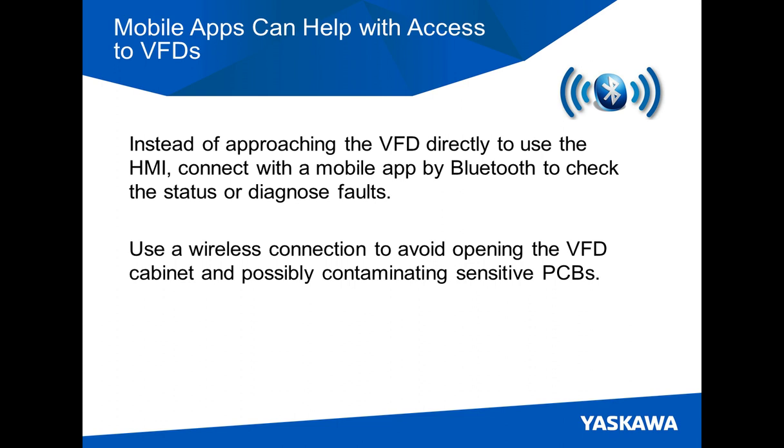So let's talk about how mobile apps can help with access. Instead of approaching a VFD directly to use the HMI, you could connect to the VFD with a mobile app by Bluetooth to check its status or diagnose faults up to 10 meters away or 32 feet. You could use a wireless connection to the drive to avoid having to open up that cabinet that we just talked about and possibly contaminating the VFD. Or even keeping yourself out of that harsh environment as a person.